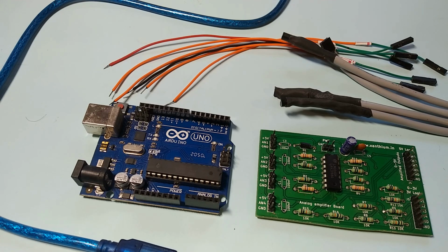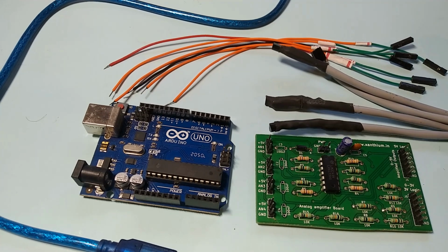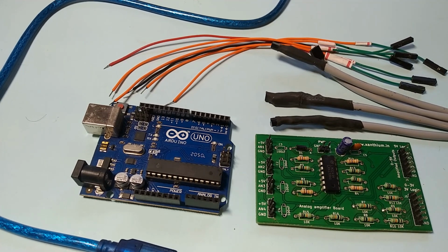Here you can see the basic hardware that is required for building our Python data logging system. Here we have 4 analog temperature sensors. This one, the one in black, consists of LM35 temperature sensors, which will generate voltage corresponding to the ambient temperature. Now we have an amplifier board, green board here, that is used for amplifying the signals from the LM35.